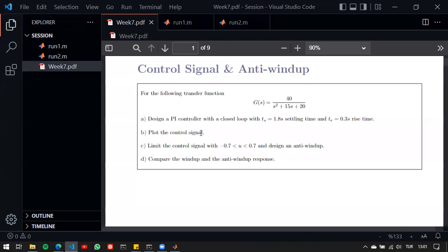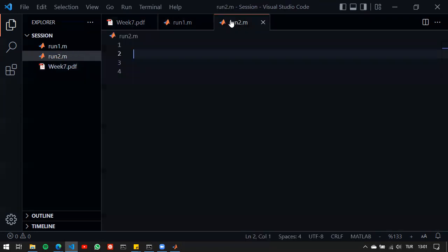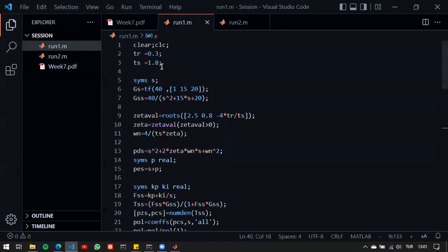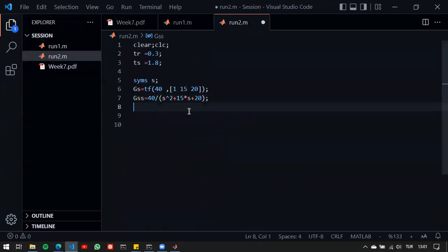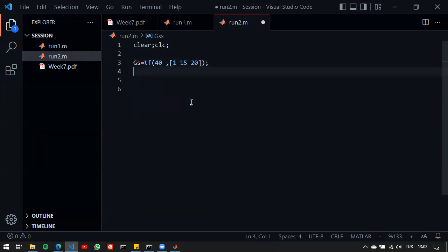Now, first of all, we can use this transfer function here and convert this into a state space realization. We'll do that. And then we'll just discretize it in order to use difference equations, and then code it so that we have basically a discrete simulation here, and then we'll implement our controller and have the closed loop. Since we are doing everything manually, we'll have full control over the whole feedback structure, because we'll generate the error ourselves, the integrator ourselves, everything. I'm not going to use this part here. I just need the transfer function itself.